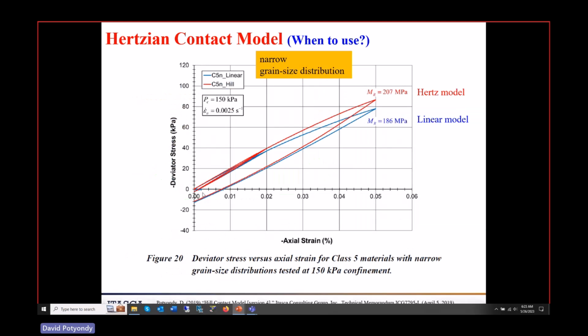What we do is we apply a strain of 0.06% or 0.05%. We basically squeeze it and unsqueeze it. And we're measuring the stress on that, the deviator stress. As we squeeze it, we keep measuring how much the axial load is changing. So we actually get, oh, this is good, a hysteretic response. Notice the stress is still there when we're done, because there's this nonlinear behavior that's happened.